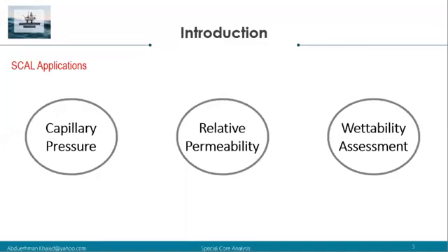And it's quite interesting that the capillary pressure curves provide means to estimate the fluid distribution versus depth, independently from logs. It's quite an independent approach from logs. So if you have uncertainties in the logs, it's a really good tool to help us determine the fluid distributions versus depth. And then we have the relative permeability data, which is widely recognized for the prediction of oil recovery during the displacement by water.